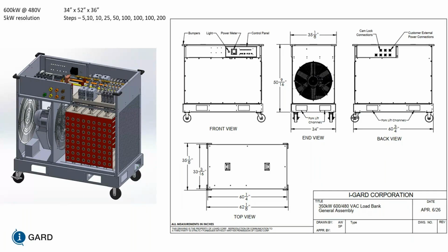Is it possible to integrate the load bank with a SCADA system to monitor efficiency? Yes, it is. We can provide all the outputs you require to monitor which contactors are closed, when to start. The normal process is you start your generator and you have voltage on the load bank. Then you can start playing with the load bank loads, and you can do that through any means.